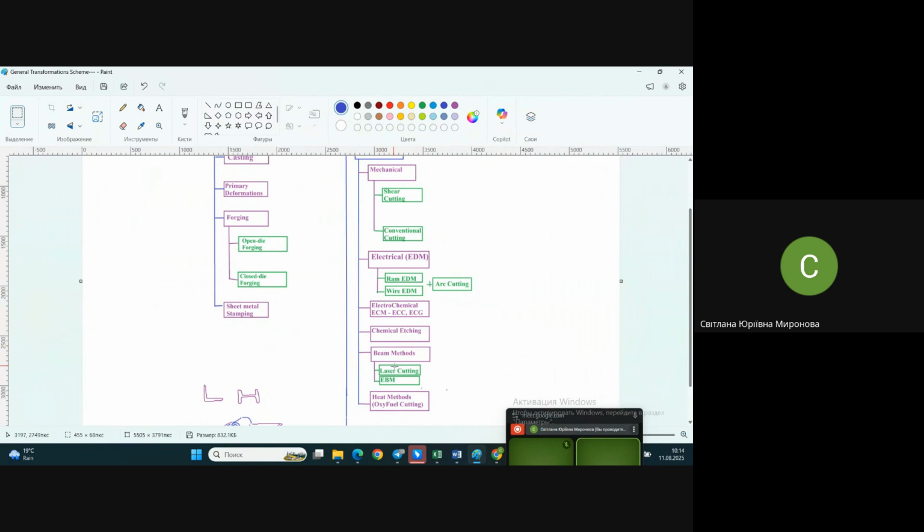Moreover, some features may be different. When you're cutting something by milling, in corners you always have fillets equal to the radius of the mill. It's easy to imagine.